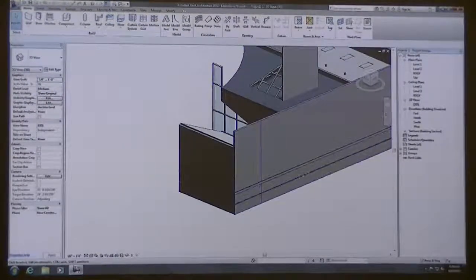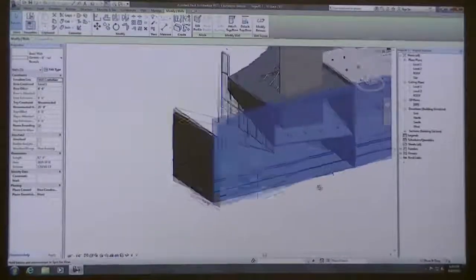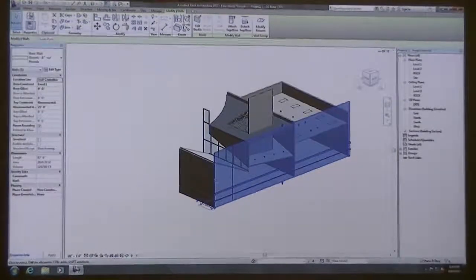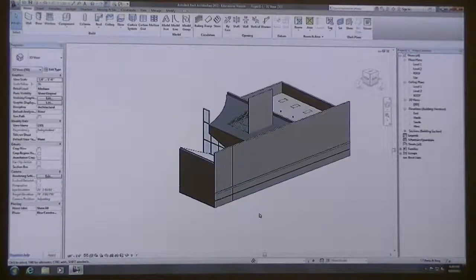So in large walls, if you've got a wall that's spanning, I'm not sure what the length of this one is, 82 feet 6 inches, most likely you're not going to have a wall that's just completely blank. If you ever look at even stucco, you have to have reveals every 10 feet or 20 feet or 30 feet or something like that. You have to have construction joints.